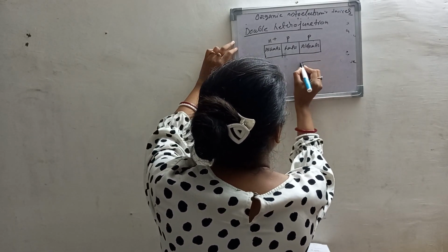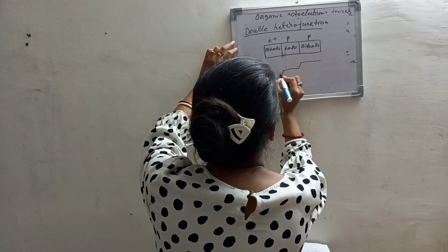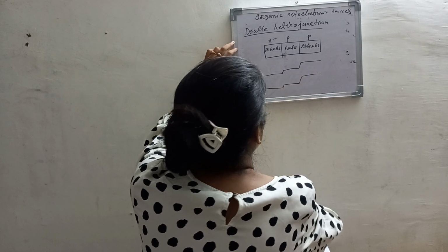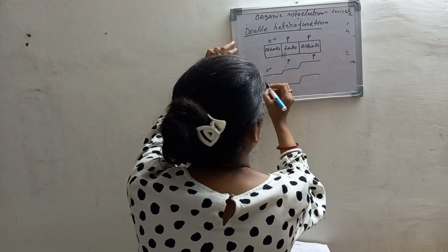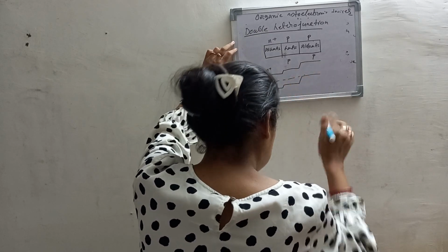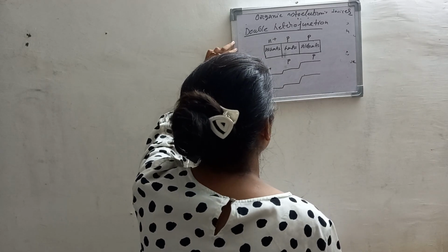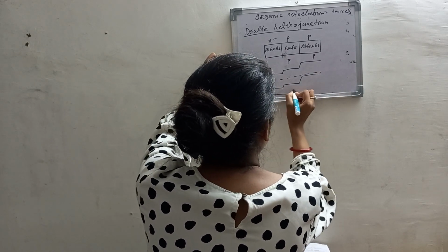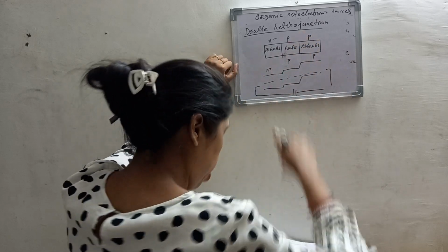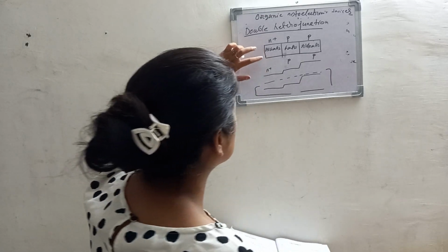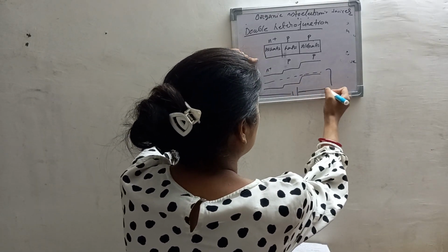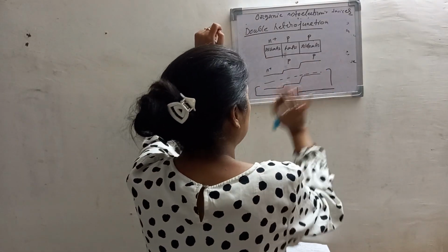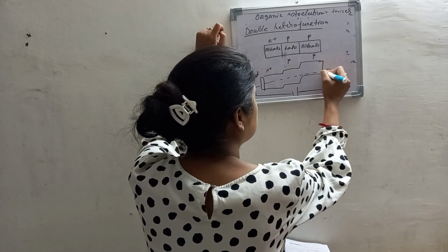Here, the band diagram. Okay, the N-type. Now we can also apply the forward bias voltage here. Okay, to the N-type semiconductor we have to apply the negative voltage, and to the P-type semiconductor we have to apply the positive voltage, right? So now we can see this is the N-type and this is the P-type, right? Here it is cathode, here it is anode.